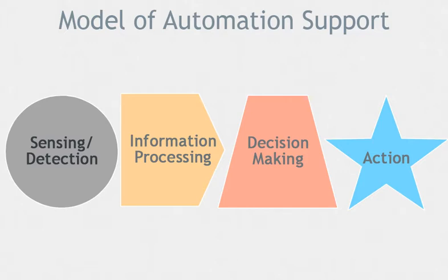You give them the necessary information without providing too much so that they ignore the important stuff, and without providing the information too often. One of the best examples of this is the gear up indication. You want to make sure that the alarm sounds only when the person is intending to land and when they've reached the point where they should have put the gear down. If the alarm sounds too often, too soon, or does not capture their attention, then they could simply ignore it.